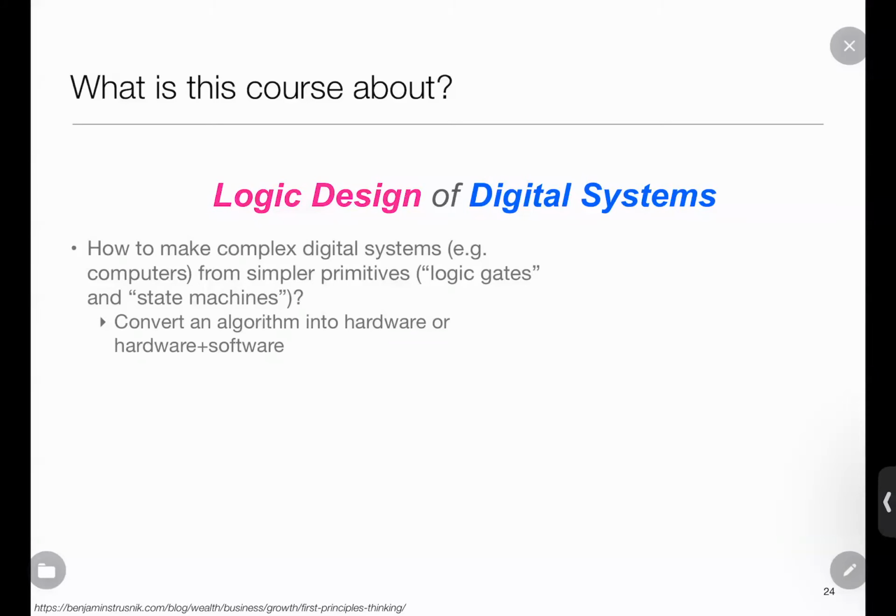This is very similar to what used to be relays. Even now, in many places like your HVAC system or your pool system, you'll find relays, which are made using a solenoid with a mechanical part. You supply AC current, the solenoid charges up, the mechanical part moves, and the switch closes. That's how we switch very large amounts of current, like in a pool motor. So we work with relays there. Semiconductor technology is getting there, but is still not very good at switching huge amounts of current. Those relays are often called contactors.